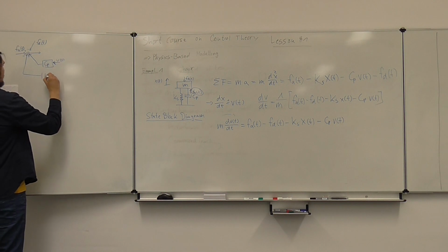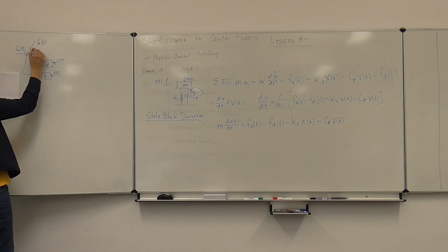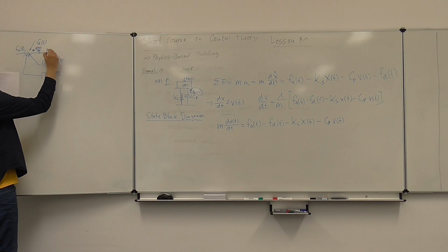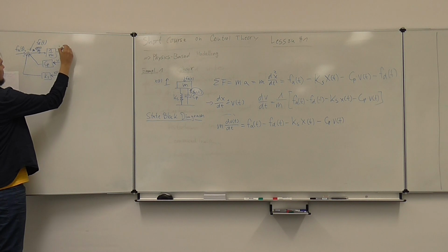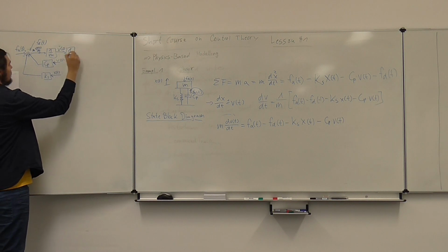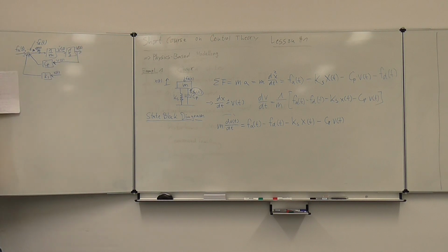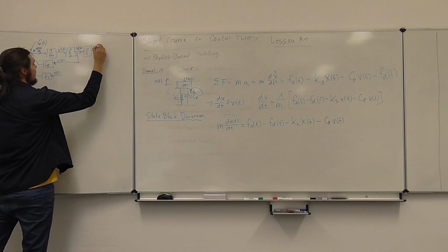There will also be x(t) going back, right? Which means this here will be m dv(t)/dt, which also means 1 over m. We get v dot of t, and with an integration, we get v(t). So we can close this here. And another integration yields us x(t).